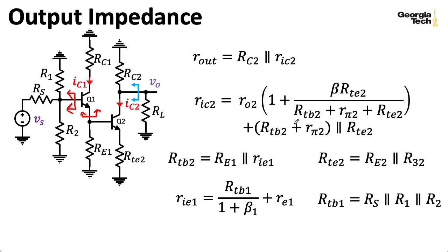But if you just think through it step by step, it's a bunch of very small computations that you just sort of pile on top of each other. Note that through this series of dependencies, the output impedance does depend on the output impedance of the voltage source that's feeding the amplifier. That's an aspect of BJT-based amplifiers that I don't think is widely appreciated.